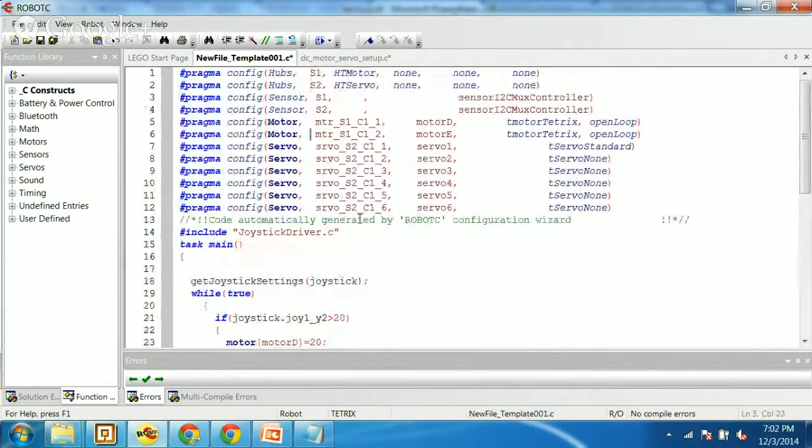All right. Have this here. And so Rishabh, can you explain the code once more? All right. So yeah, surely we can do that. So we first start with the basic configuration of the motors and the servos. So we go to robot, we go to motors and sensor setup, we select the external controller, we configure the controllers, then we go to the motors and servo setup, we configure them, and we have a bunch of lines automatically included to our program.